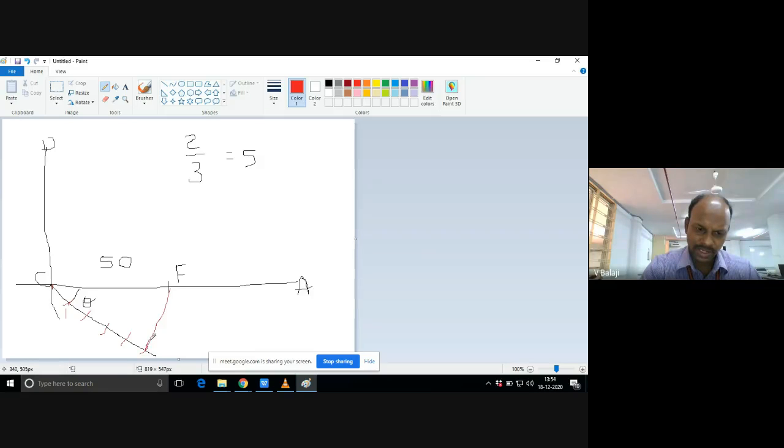After drawing this line with an ordinary scale to the focus, what you have to do is set your mini drafter scale. Your mini drafter is L shaped, right? What you have to do is match one scale to this particular line, the line you have joined from the fifth arc to the focus. Match the drafter scale to this line and tighten the mini drafter knob.